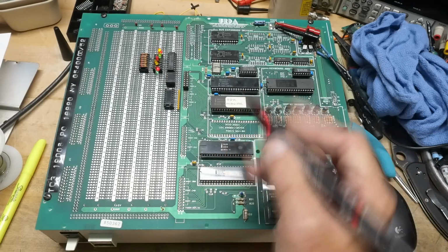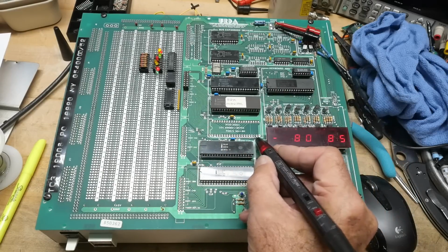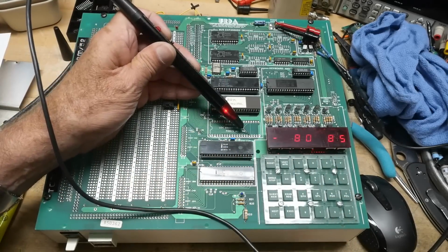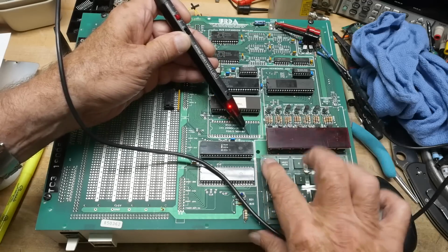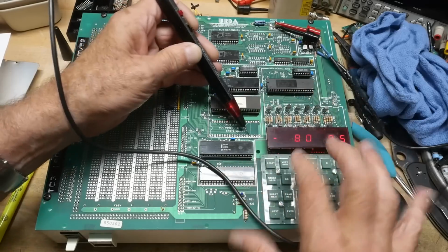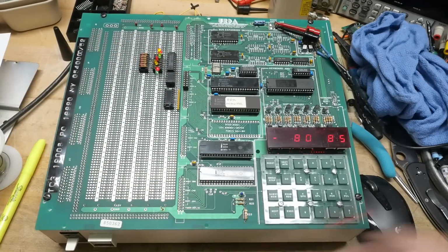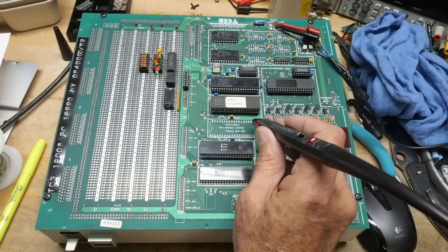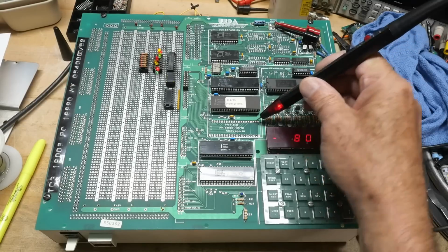And this is really good. You can examine your data lines. So here's some data lines, and you can say, okay, I've got actual activity on my data line. But let's say that something happened and you no longer have activity on that line. I've held down the reset button and it's no longer clocking, okay? So a lot of times you can take a look at, is maybe the address 12 line doing something, you can program that and you go, yeah, that's good.